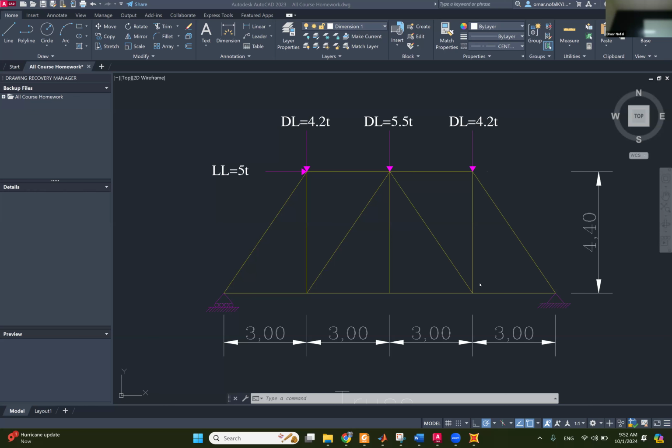Okay, that's the material. Cross sections are also a big thing. If this cross section is a beam 50 centimeter by 50 centimeter, you need to define a cross section that is 50 centimeter by 50 centimeter. If it's a steel I-beam that has a flange width of, I don't know, 50 millimeter, and the height is 100 millimeter, you enter what is in your problem, okay? So the definition is a very, very important part of modeling in any software.